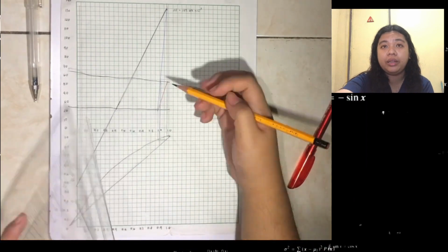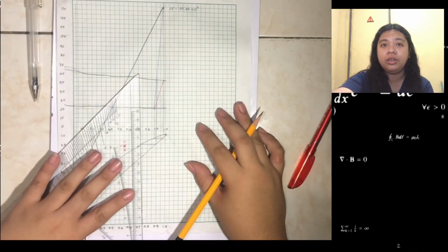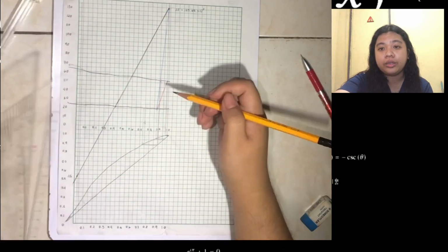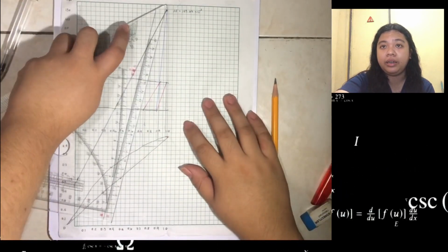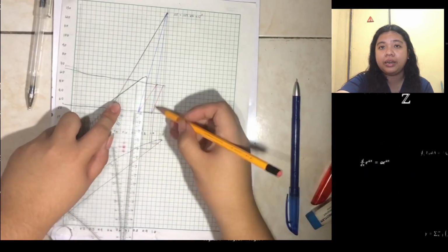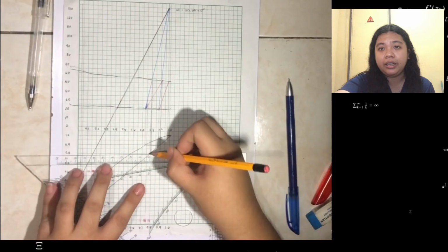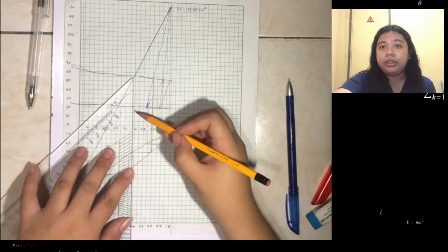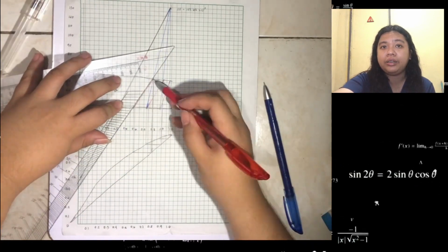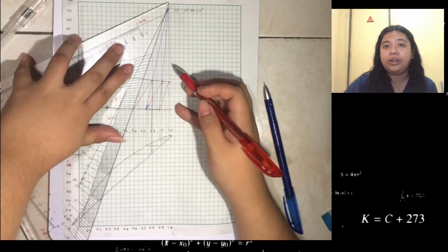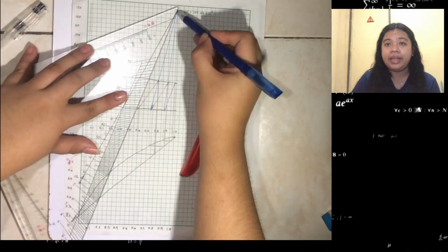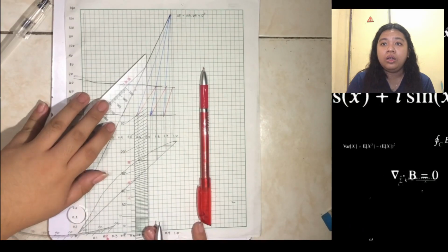So we will now begin to identify the number of stages. Create a point on the saturated vapor line that intersects 0.97 and create a vertical line downward till it reaches the 45-degree line. Create a horizontal line until the equilibrium line, and then a vertical line to the saturated liquid line, and create a point. So that will be our HL. Create a tie line from the two points we created.